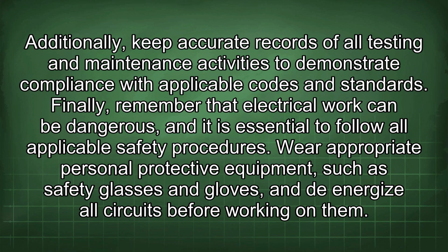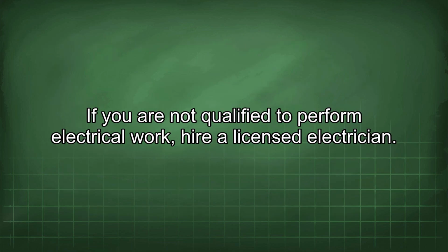Finally, remember that electrical work can be dangerous, and it is essential to follow all applicable safety procedures. Wear appropriate personal protective equipment, such as safety glasses and gloves, and de-energize all circuits before working on them. If you are not qualified to perform electrical work, hire a licensed electrician.